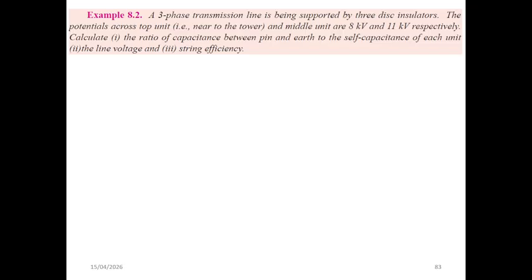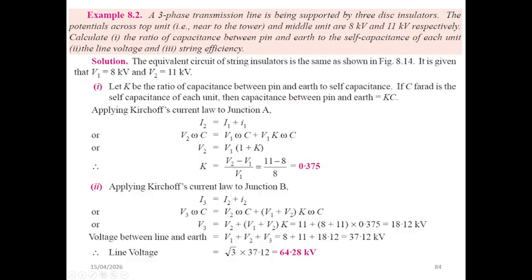Furthermore, the total line voltage and the string efficiency can be calculated, and this analysis helps highlight the impact of capacitance on voltage distribution, and demonstrates how unequal voltage sharing affects the performance and efficiency of an insulator string in a high voltage transmission system.